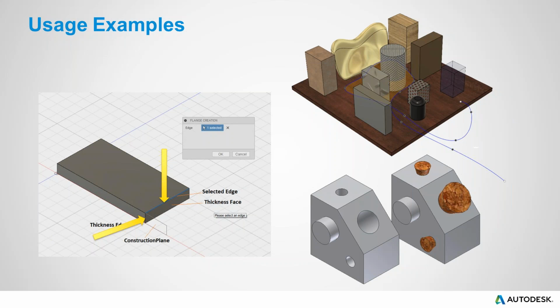Yeah, that could work too. The CoEdge would be in a different direction for the internal one, so that would be another way. Is that loop an internal edge or not? Although that doesn't totally work. It works for the edge on the outside of the boss, but not the edge where the boss connects into the body, because that would also be an internal edge. Okay. Did you do alignment at the end?